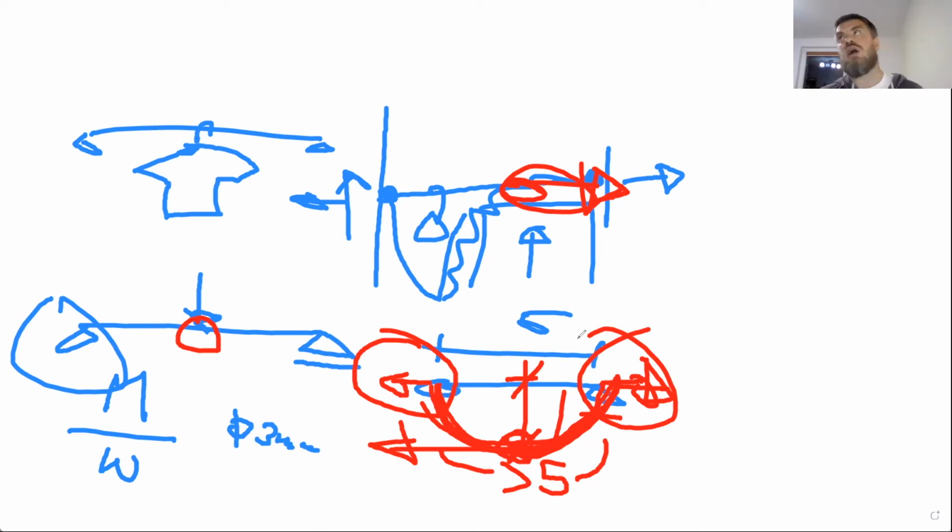So it's not like, oh, I have a structure and I didn't use nonlinear geometry, so I'm on the safe side. This is not how it works. The nonlinear geometry is always there as your model deforms, and it will simply push the load to different random directions, make hooks in your structure and so on. And this is a dangerous thing to ignore. So yeah, if I would have to explain what a nonlinear geometry is in a few minutes, I think that would be it. Nice.